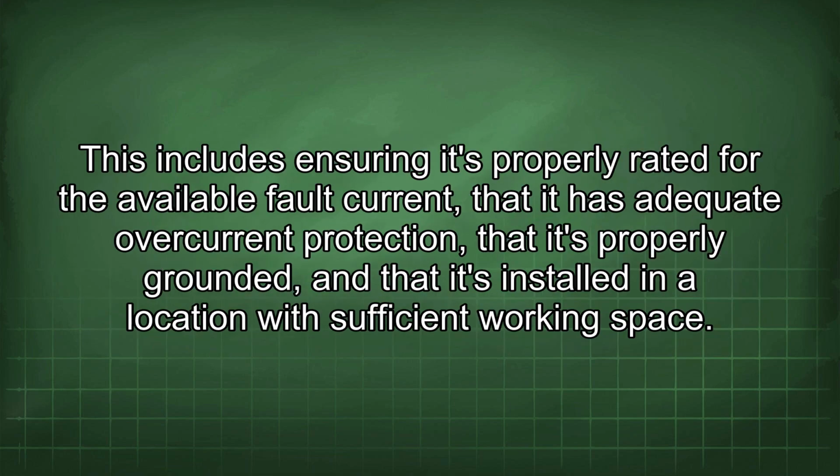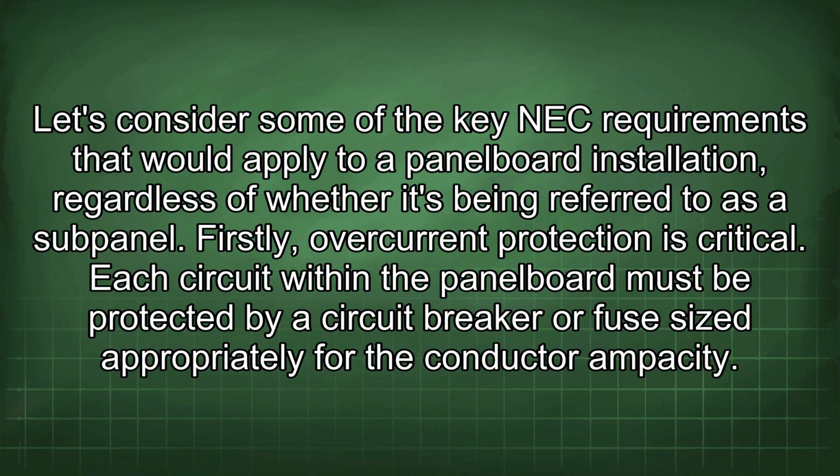This includes ensuring it's properly rated for the available fault current, that it has adequate overcurrent protection, that it's properly grounded, and that it's installed in a location with sufficient working space. Let's consider some of the key NEC requirements that would apply to a panel board installation regardless of whether it's being referred to as a subpanel.